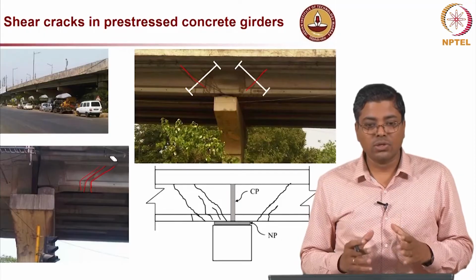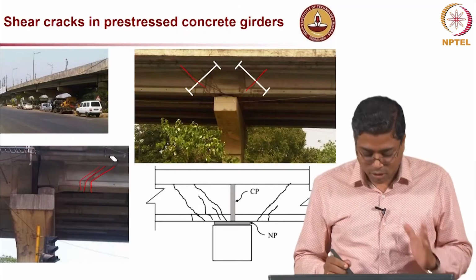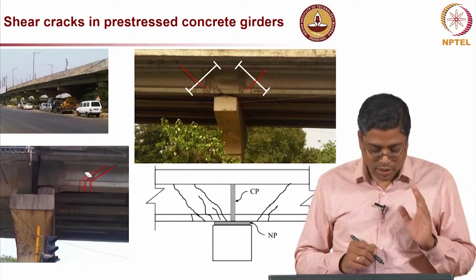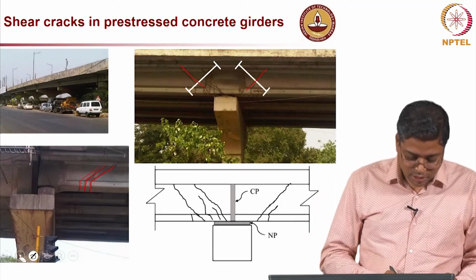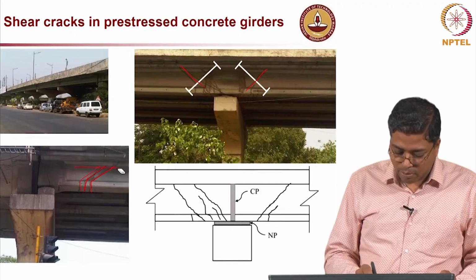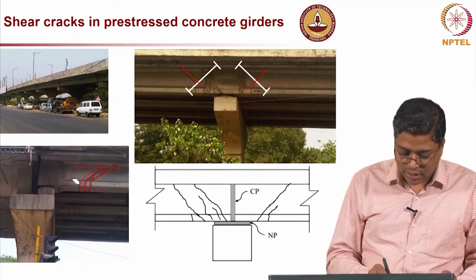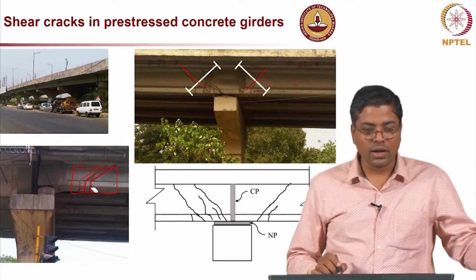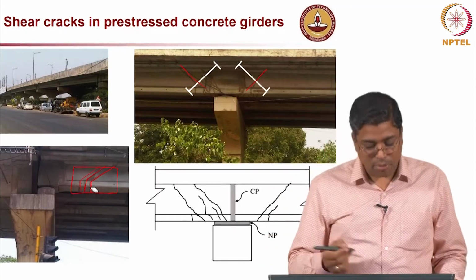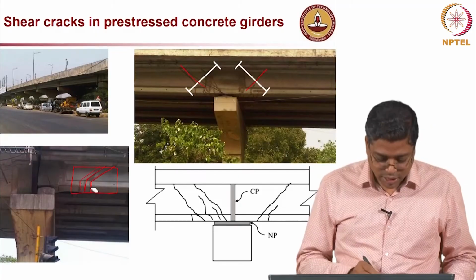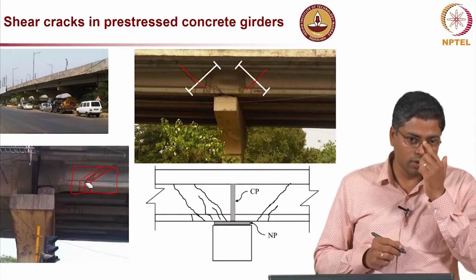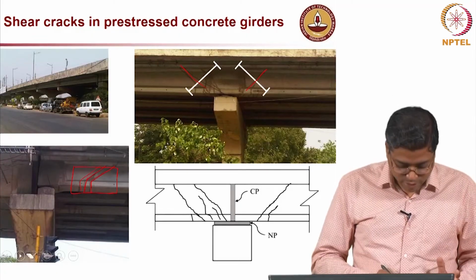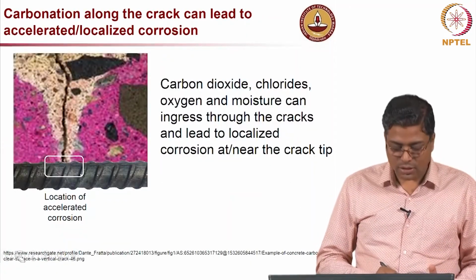So, you have to ensure that oxygen molecules or water molecules cannot penetrate through these cracks. That is very, very difficult to achieve unless you really provide a proper cover. Instead of just filling the crack, we may want to go for a proper cover and covering layer. That might be a better option than just filling the crack with epoxy. The best thing is to prevent cracks, or do a better design so that these cracks do not occur.